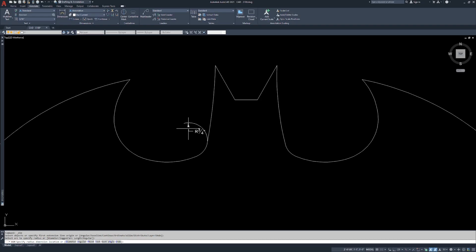Now in this case, it's giving me a ghosted line implying that radius. In most cases, you don't want that because if it's a mechanical design, it's going to confuse somebody. So the best thing to do is to pull the radius to the outside of the curve because it gets rid of that implied circle. So I'm going to pull out here and I'm just going to left click and we're back in the dimension command. Dim, select objects. So that radius is good. That radius is good. And all I'm doing is left clicking. Left click, pull it away.